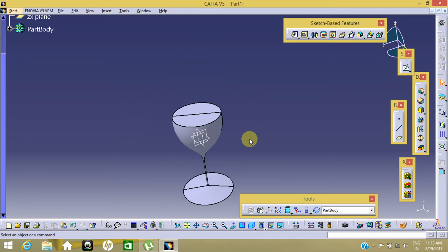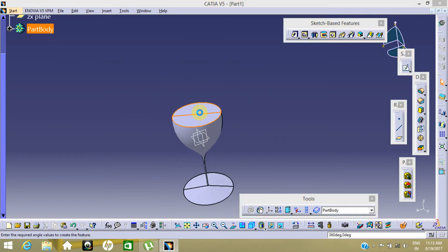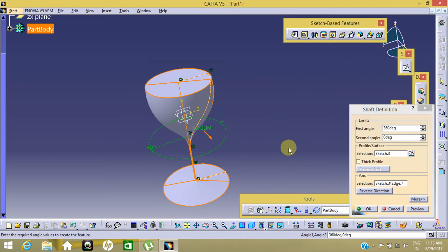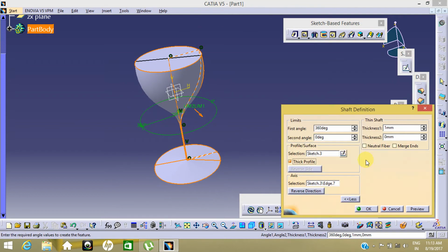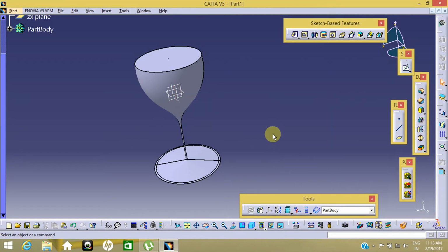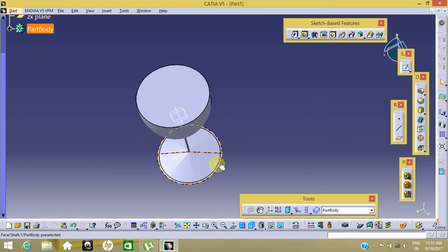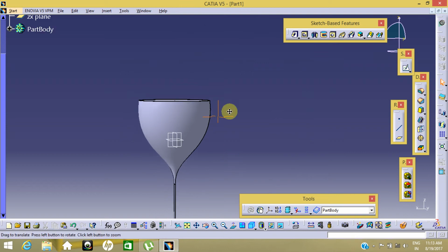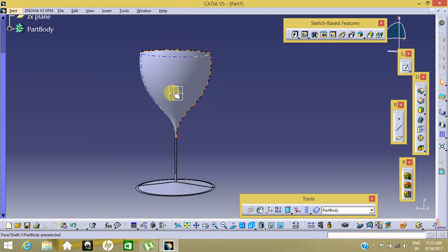So this dynamic section, you can see this dynamic icon is used to cut the body into half. So you'll see this body is now being removed from inside material, that is a thickness of 0.5. Okay, you can see here. Now I will turn it off and make this body again a thickness-free, a solid one. Okay, just make it preview and okay.